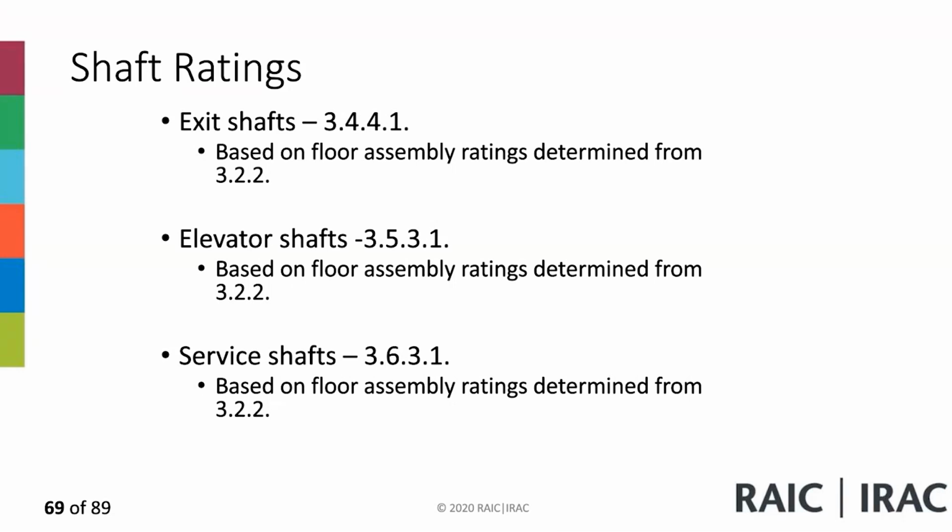If I have a 1.5-hour floor assembly rating, I need a 1-hour service shaft rating again. If I have a 1-hour or 45-minute floor assembly, I need a 45-minute shaft. If I don't have any rating for my floor, I don't need any rating for my service shaft. So that's in Table 3.6.3.1.